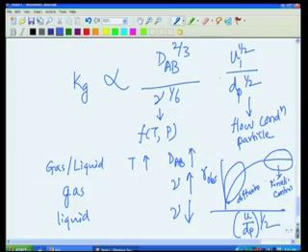We can actually find out by doing experiments, with the same concentration, same temperature, same pressure, everything the same, except we change the velocity or the diameter of the particle. If we get results something like this, we can identify the regimes under which reactions are kinetically controlled, that is, the rate is independent of variation in u or dP, then this is that region. If it is the diffusion region, then the rate will increase as we increase u by dP, and then of course, there is a transition region.